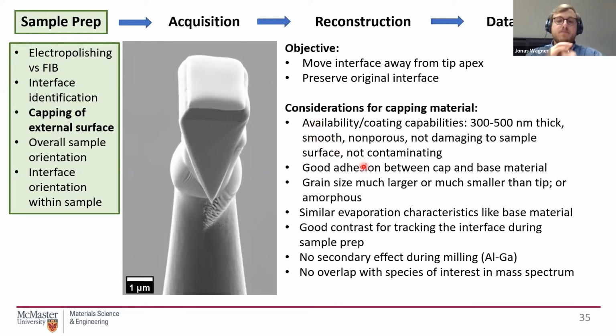Then the next step, absolutely crucial, you need a good adhesion between the cap material and the base material. If the adhesion is not good, you will load your sample into the LEAP, and you will get fracture at one point, and you won't be able to extract any data that you're interested in from your interface at all.